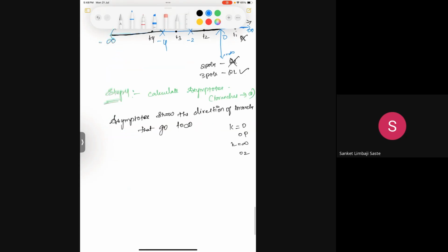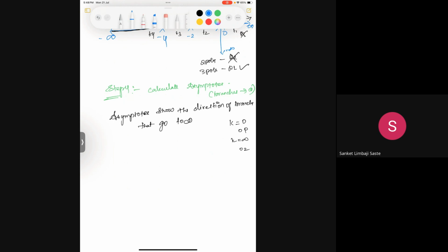Okay, so now, this will be more helpful if the number of poles is greater than the number of zeros. So there are 3 poles and 1 zero. How will you determine which pole will go to this zero? If you calculate the angle of asymptotes for each pole, you can precisely know which pole is going to end up in that 1 zero, and which other 2 poles are going to go to infinity. So if there are more poles and fewer zeros, that many branches as there are zeros will start from poles to zeros. The other branches will move to infinity.